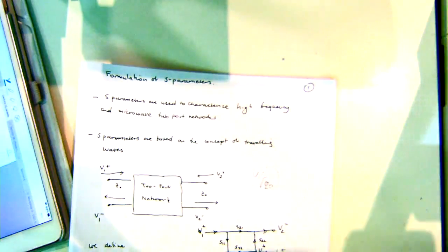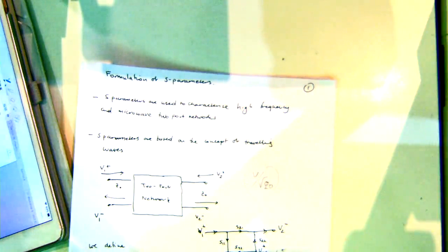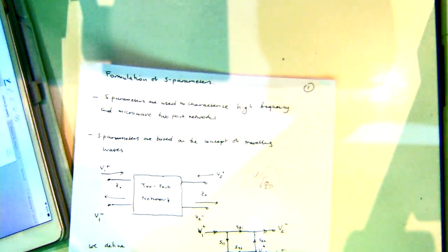This means a function. So this is the admittance, which is 1 plus jB. And when you move to this point and shift it, we want to add admittances, right? But remember, you're now on an impedance circle. So this is impedance, but now you want to add an admittance.